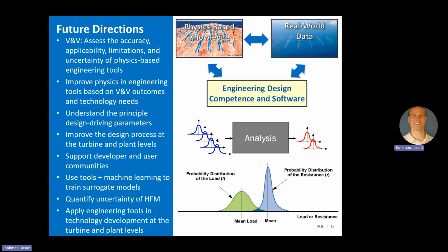As we mentioned, there are definitely physics improvements that we've been working on. BEM is one that's recent, but there's quite a few things going on, hydrodynamics and so on. A lot of this is driven by what we see in the V&V. We find an issue, like with high skew it doesn't work, or it's way off, so we go back and try to fix that. Any V&V work you're doing as well, you find issues, like it's not giving the answer I expect. You can try to calibrate it away, or you can actually fix the physics. We've been doing a lot of that.